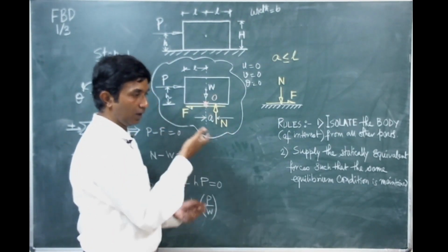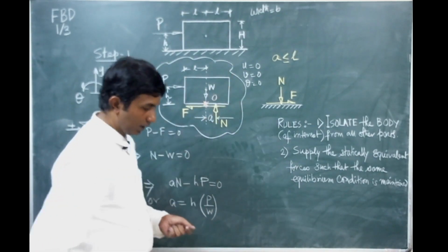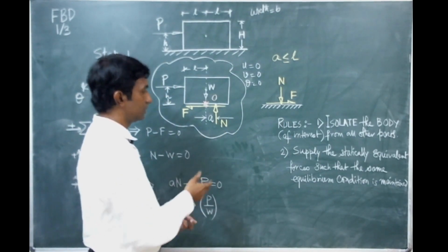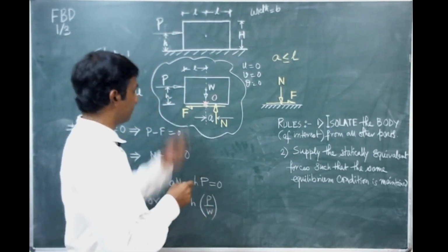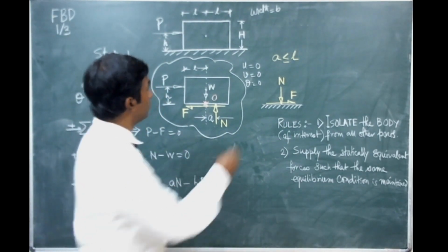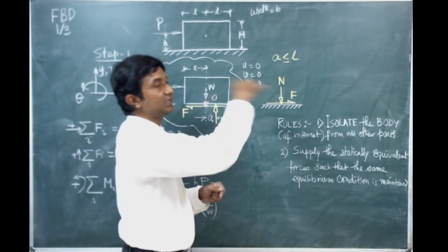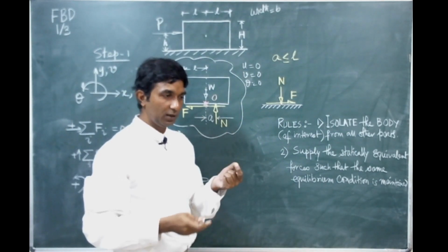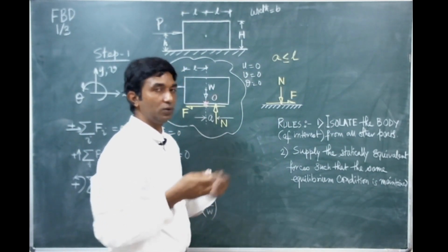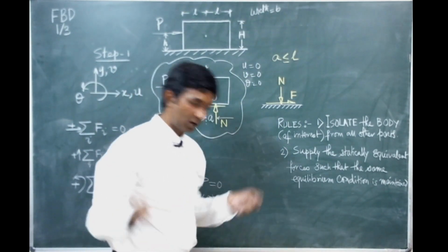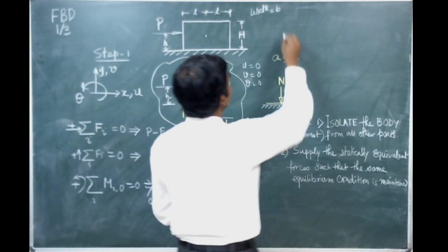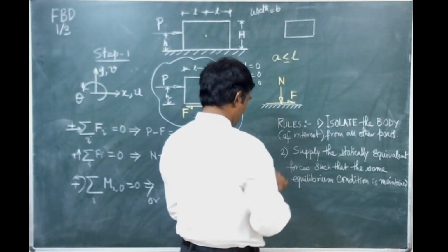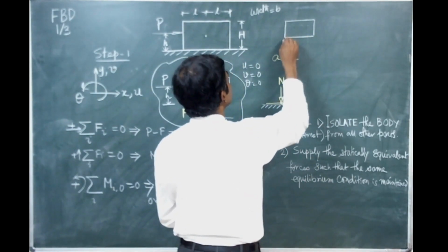Now let us see whether this N conveys the actual representation of the contact. What is this contact offering, whether N and F say everything about that or not. You know that it is distributed; you do not have a single point of contact. You have a zone that contains an infinite number of points, so you basically get a distributed force, a distributed intensity.